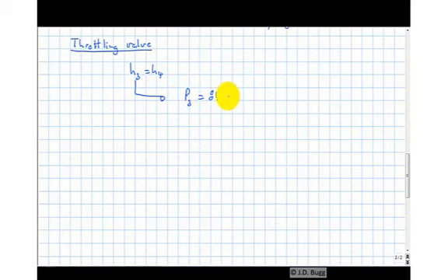So just as we did in point 1, we need to first of all look up the saturation temperature, and it turns out that at 8 bar the saturation temperature is 31.33 degrees C, and therefore, because it's subcooled by 5 degrees, the temperature at 3 is 26.33 degrees C. So we have a subcooled liquid coming out of the condenser, subcooled by 5 degrees.